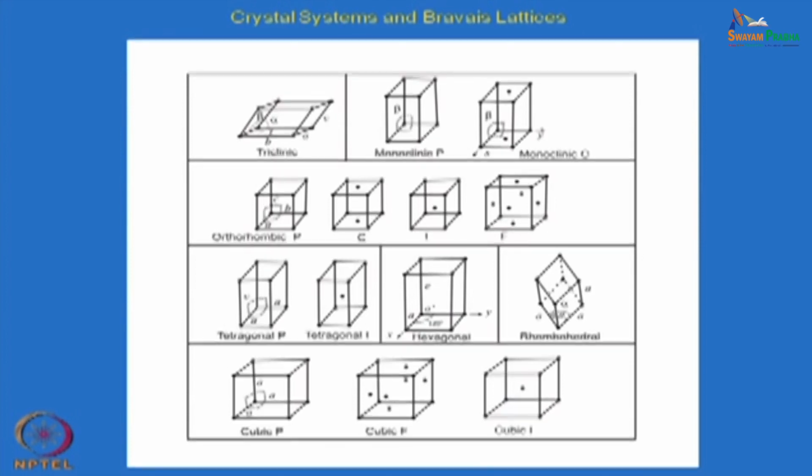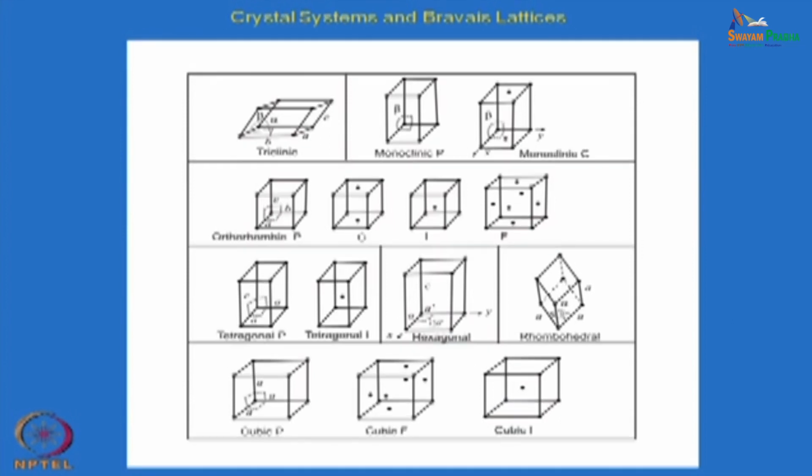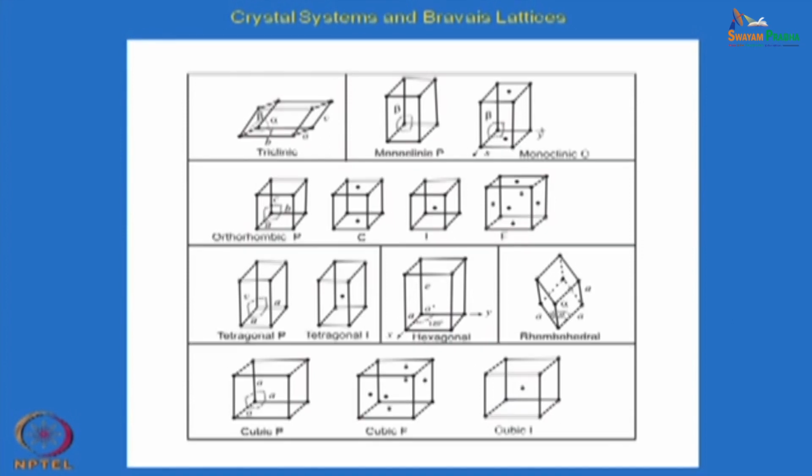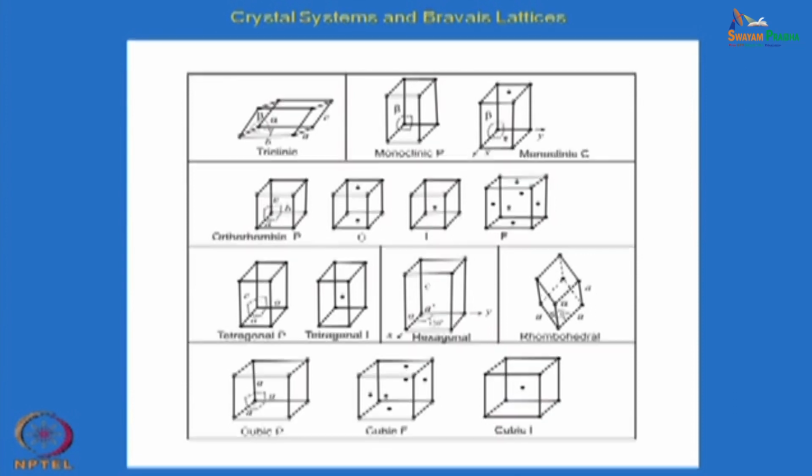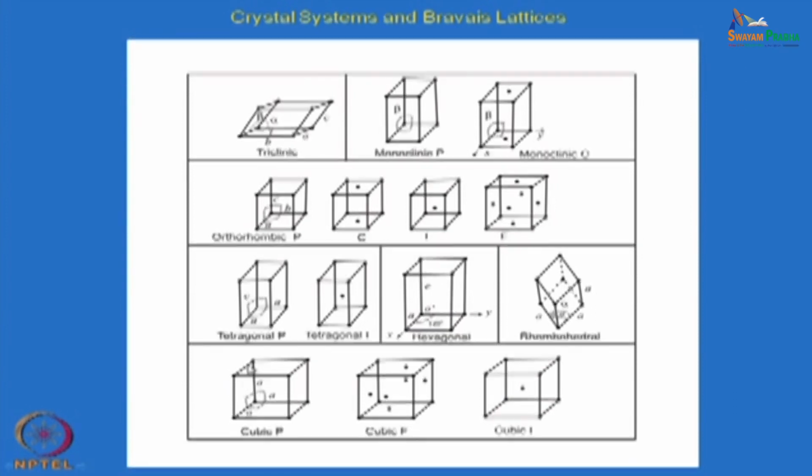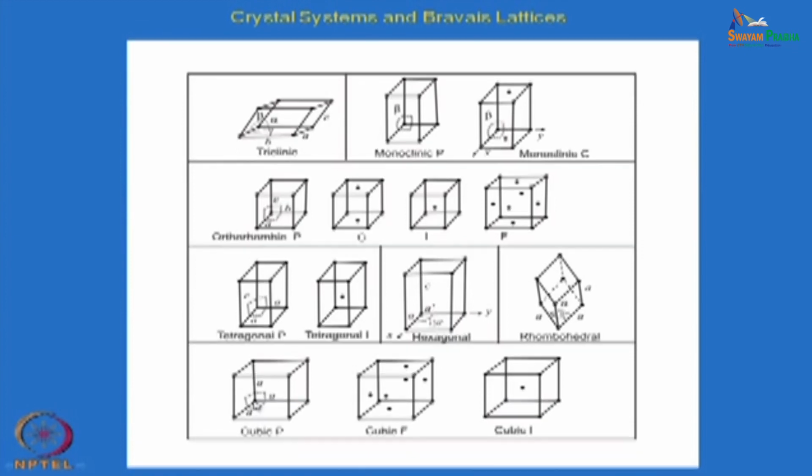Sometimes we talk about hexagonal crystal structure, sometimes cubic crystal structure. We have also discussed monoclinic, for example, in zirconia. So, there are different kinds of symmetry elements, and it may not be possible to discuss everything here. However, very briefly let me tell you, there are 7 crystal systems, depending on the relationship between the 6 parameters, what we call the